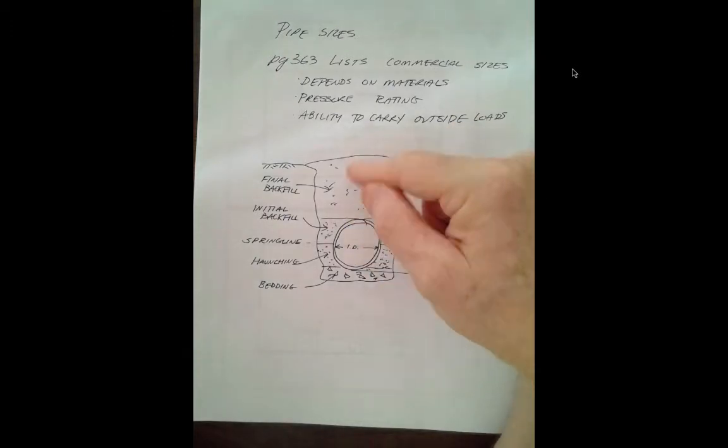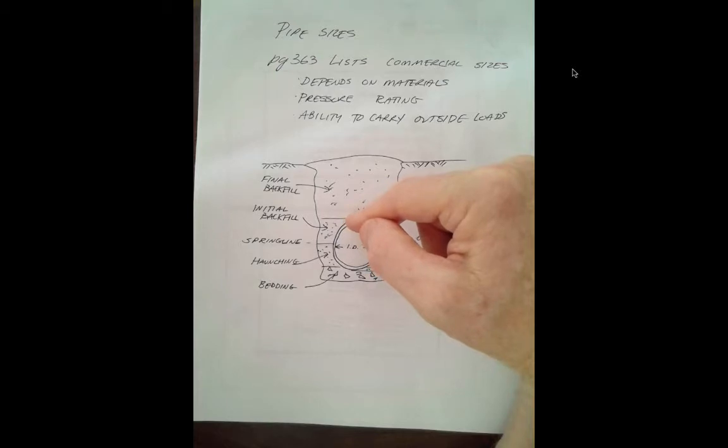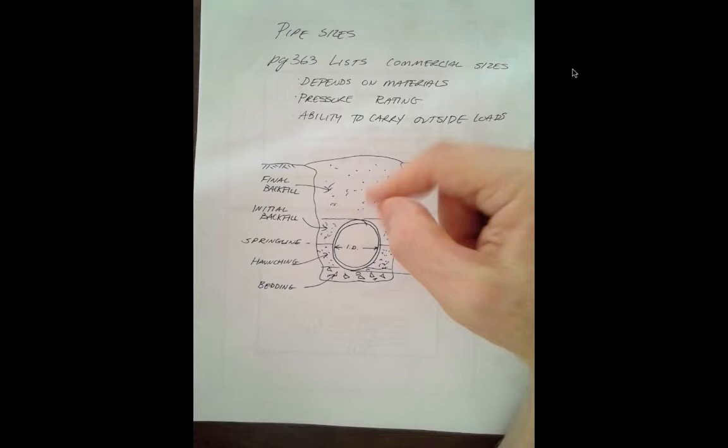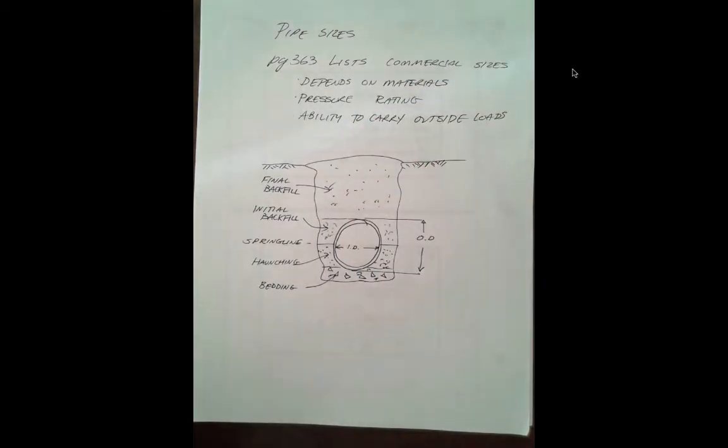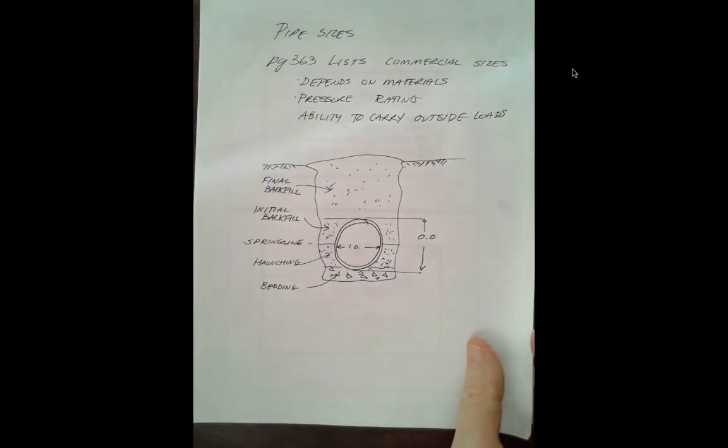And so this soil overburden is a substantial amount of weight on top of the pipe, and the pipe has to be able to resist that load from the outside trying to crush it, resist the pressure load of the liquid on the inside trying to get its way out of there, and do it all for a reasonable cost. So point is, in our pipeline designs, in a practical sense, we also have to worry about the structural aspect, which is not part of our book.